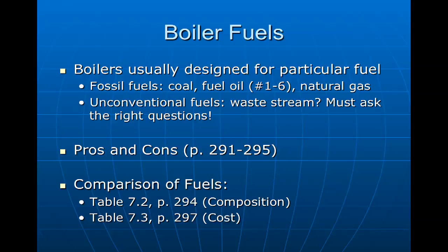If you're in Georgia, where peanuts are grown and packaged, quite often you may have a whole lot of peanut hulls, and those peanut hulls could be used. You'd be able to determine what the BTU ratings are for that waste stream, so you can determine if you have a reliable source of it. It's all well and good to put in a waste stream boiler, but if you don't have the waste on hand, then you'll be trucking it in from other places, and that may be more difficult than just opening up a natural gas line.